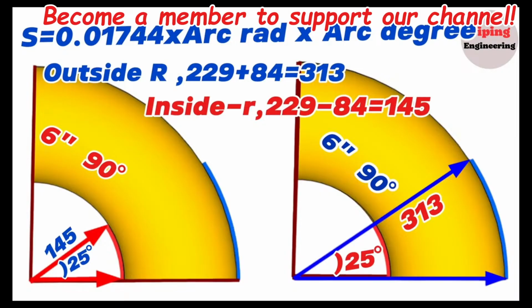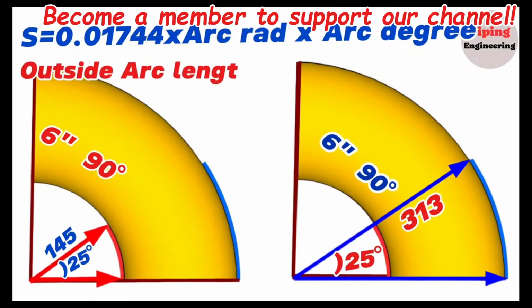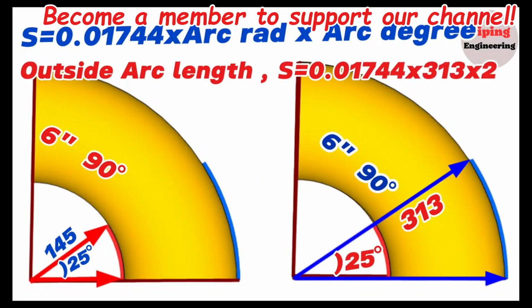Now, using the arc length formula, let's calculate and mark the length of the 25-degree arc from the inside and outside of the 6-inch elbow. First, let's calculate the length of the blue color arc on the outside of the elbow. So, the length of the outside blue color arc, S, will be equal to 0.01744 multiplied by the radius of the arc, 313 mm, and the degree of the arc, 25 degrees.